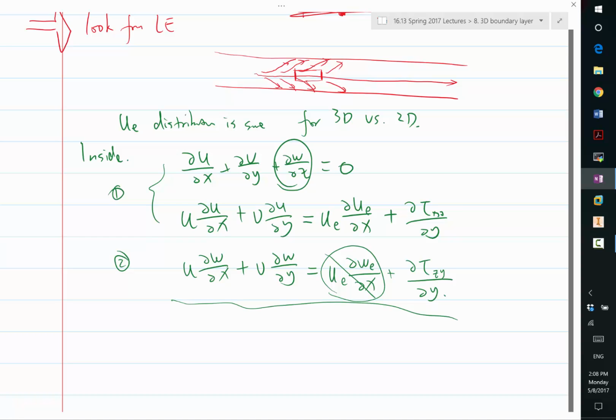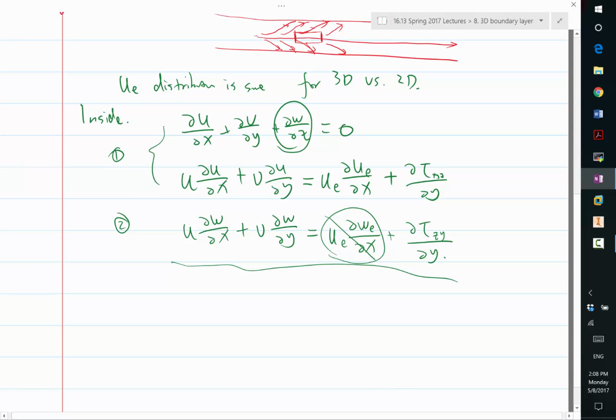And then if you impose a uniform Z flow in the Z direction, you can go through the same procedure to solve for the corresponding boundary layer, the corresponding cross-flow profile for the Falkner-Skan solution. So if you do this for the Falkner-Skan solution, you get the so-called Falkner-Skan-Cooke profiles that are 3D.